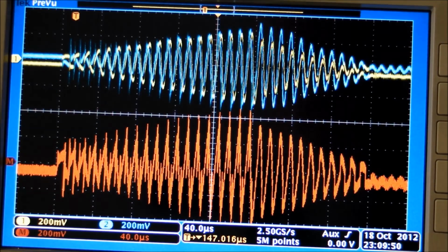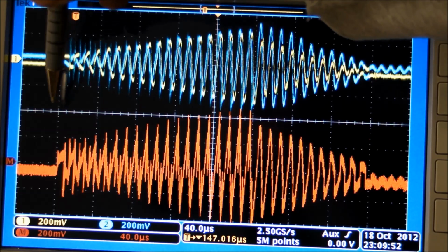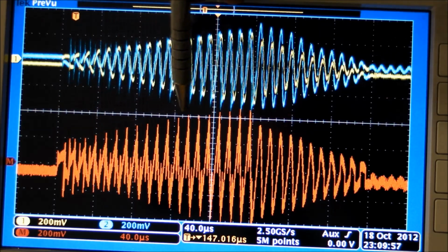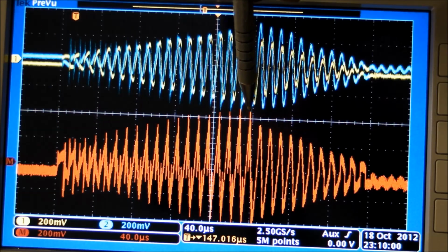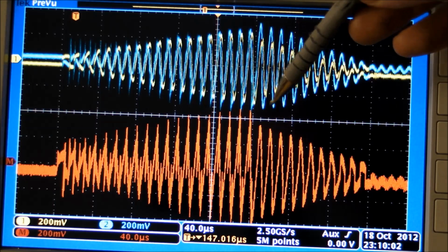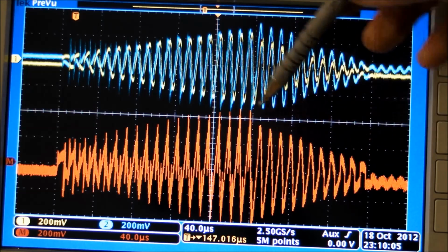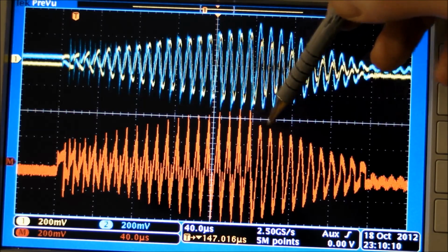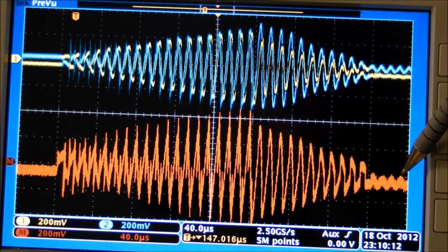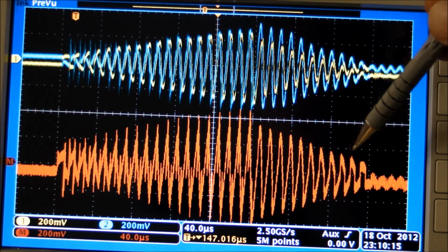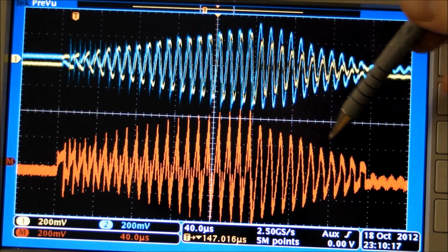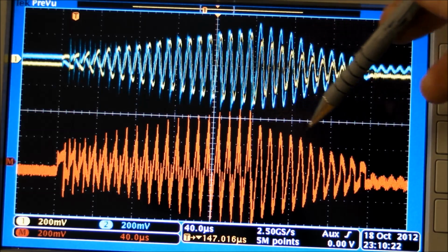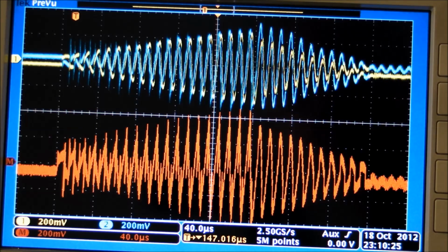And here's what we got. This one looks much better. You can see the voltage starts to build up very slowly from here to here for 200 microseconds, at which point it just decays very gradually all by itself for a period of time. And I think that it just takes a longer time to decay because the secondary circuit is not discharging a lot of energy through the spark gap discharge, for the sparks coming out of the top load.